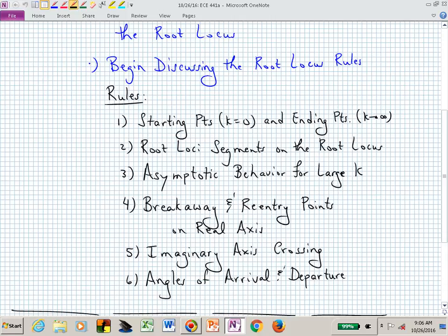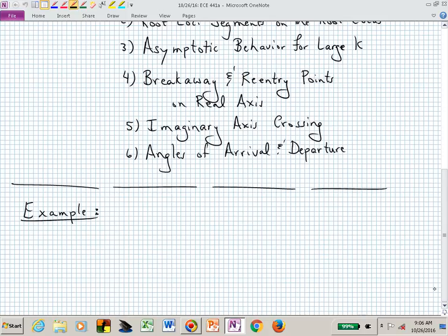And so we're referencing that sort of going off to the right on a horizontal line, and those will be our angles defined relative to that particular defining line. Let's look at an example before we get into root locus construction of how to find or how to create this standard root locus structure from a generic characteristic polynomial equation. And here, how are the closed loop poles